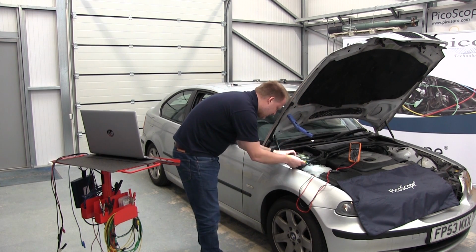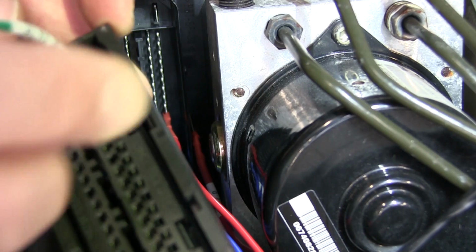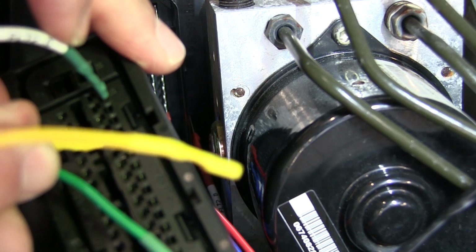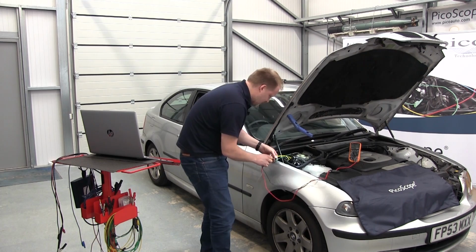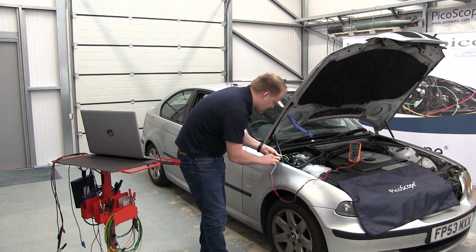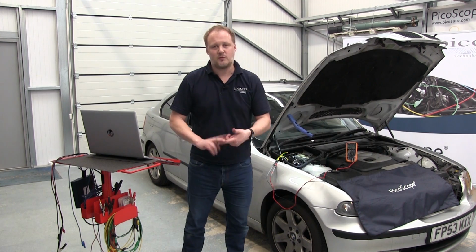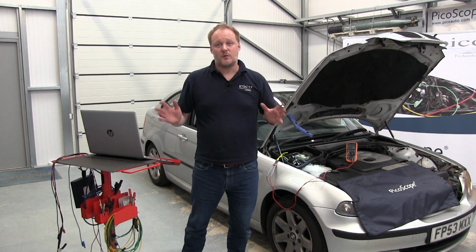Now if we look down the whole bus, again finding the same pin, so 15 there, on this side of the connector, so 15, 14, 13, 12, 11. Marvellous. Take our digital multimeter. Look at that. What do we get? Again, 120 ohms. So perfect. So we can safely say that we've got the correct terminating resistances in the CAN bus circuit, and that there are no faults on it at present.